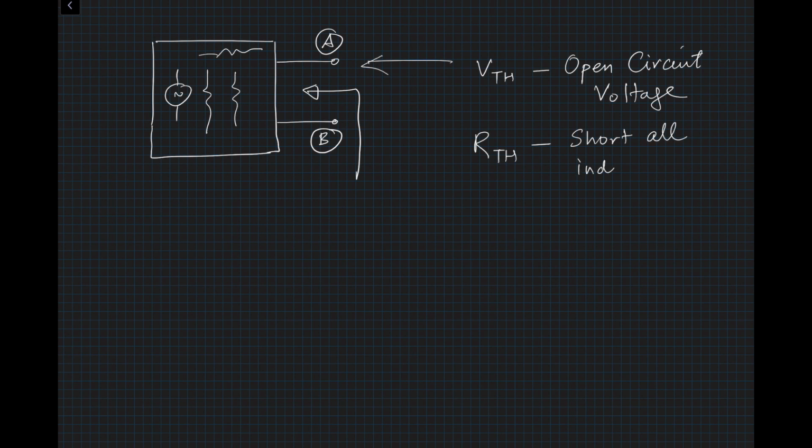The key point here is you will short all independent voltage sources, and then you will find the equivalent RTH. That's what you'll measure.